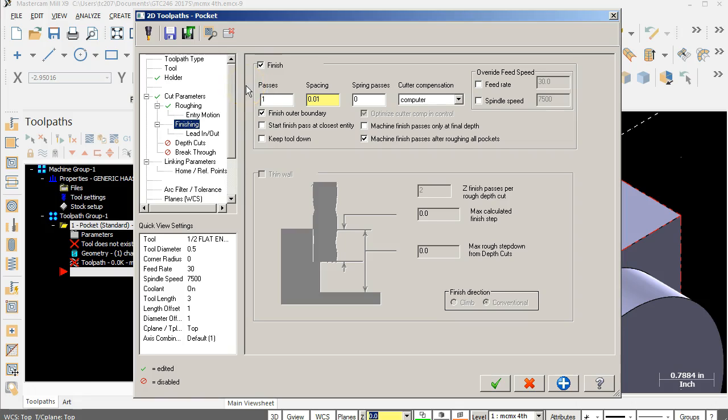All right, so go ahead and finish. Compensation will be on the wear, and let's see. I think I made those 1/4 inch deep, so we'll see if it goes all the way through. Start it, pass at close vicinity, and no, it doesn't need to do a full retract.